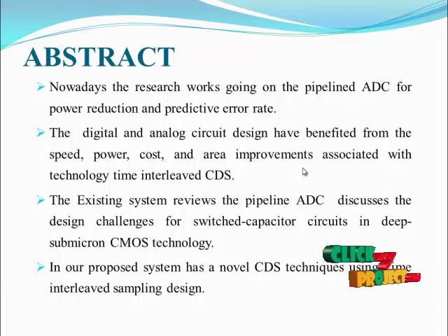To provide high gain, we apply the partially switched op-amp technique, in which auxiliary regulating amplifiers are turned on and simply attached to the low gain op-amps of the amplifying phase to form the folded cascode with the regulated gain boosted amplifiers. In this way, we reduce design effort and minimize the additional power consumption.